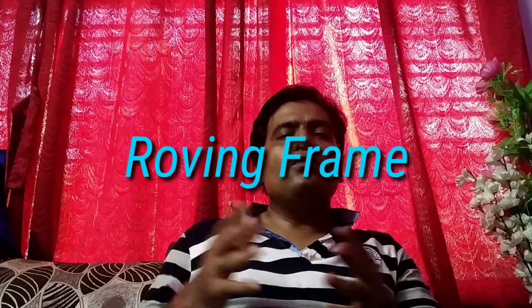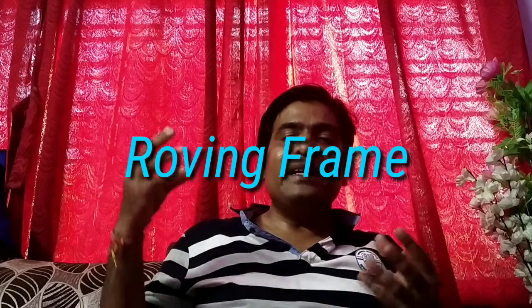And what is the motto of this roving frame? The motto of the roving frame is to attenuate the sliver and make a thinner form, and a slight twist is given in this roving so that the fibers could hold inside the roving.